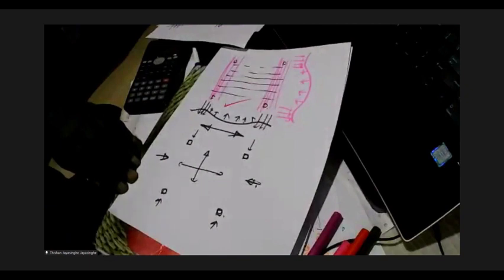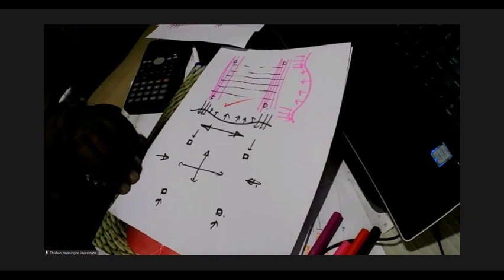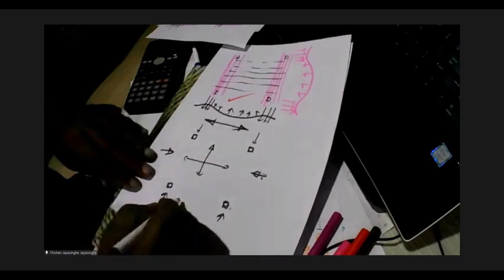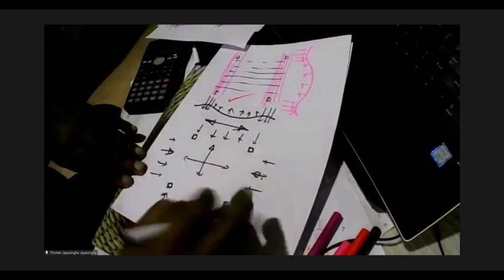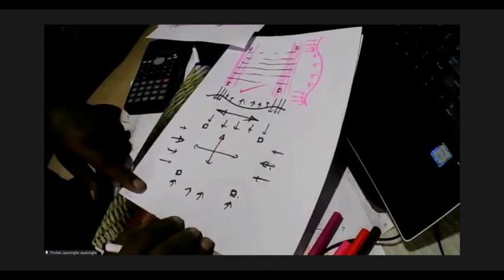Then we can see whether the stresses are okay. Once we decide on the pre-stress, we can model the slab using plate elements and find the stresses, because the PT is now applied in this direction as well, axial PT is available in this direction also, and see whether this PT can carry the effects of live loads.